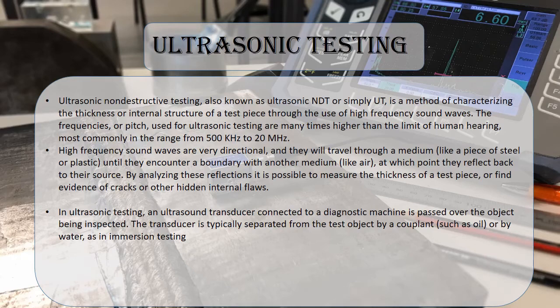kHz to 20 MHz. High frequency sound waves are very directional and they will travel through a medium like a piece of steel or plastic until they encounter a boundary with another medium like air, at which point they reflect back to the source. By analyzing the reflection, it is possible to measure the thickness of a test piece, find evidence of cracks or other hidden internal flaws.